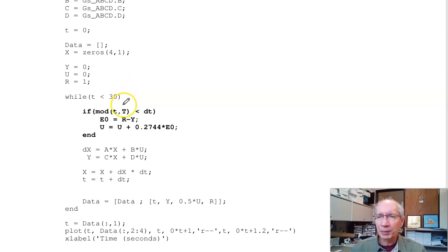So in the code, I'm going to be running every 0.5 seconds, I'm going to call this routine. The discrete time compensator is 0.277 z over z minus 1. So it says the next input is the old input, that's the z minus 1, plus 0.277 times the input.